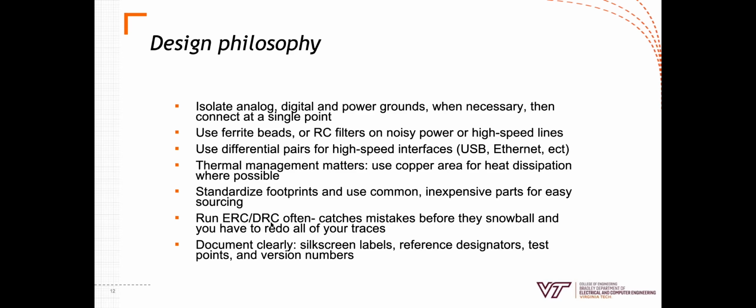DRC stands for Design Rule Checker. This is going to be your best friend with PCB design. This makes sure that the board that you designed is actually manufacturable and doesn't violate any of the manufacturer's design rules. It's a good idea to check this pretty frequently to make sure that you're not violating any of their rules. It's better to catch mistakes early so that you can fix them, so that you don't have to re-lay out your board if you accidentally make a single mistake.